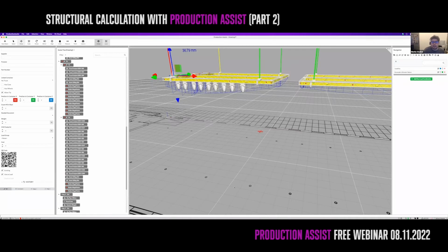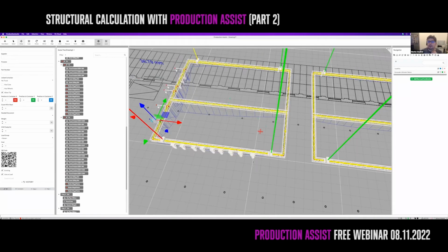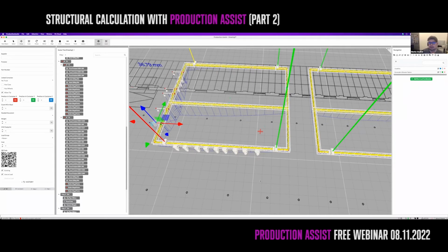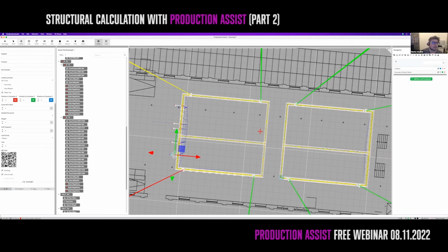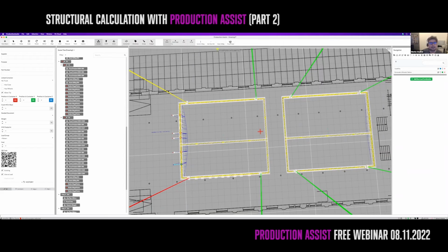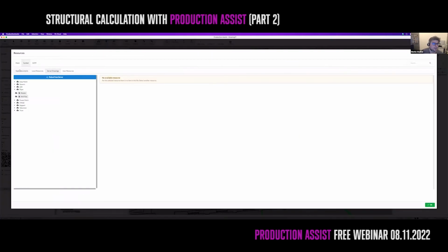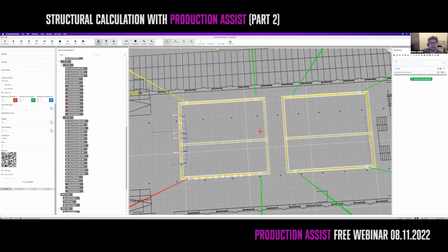As a last thing, we will insert a drop in here. A drop is something that connects 2 trusses. In order to generate something that can be used as a drop, we first need to insert the trusses for this. I'm selecting the symbol again, looking into the open drawing at what I have, and choosing the truss. I could now use again the snapping to insert this, but when I'm using the line insertion, it's actually much faster than when I would do this other ways. So I want to insert a truss that goes from here to here. Pressing OK will insert multiple trusses at once.